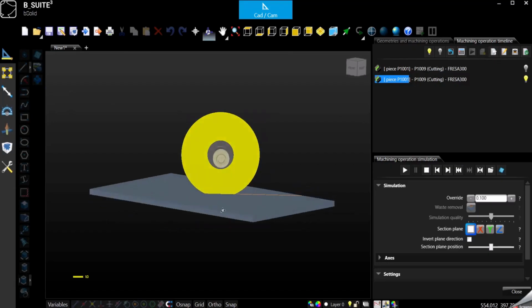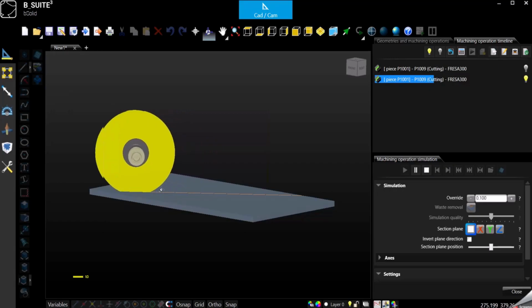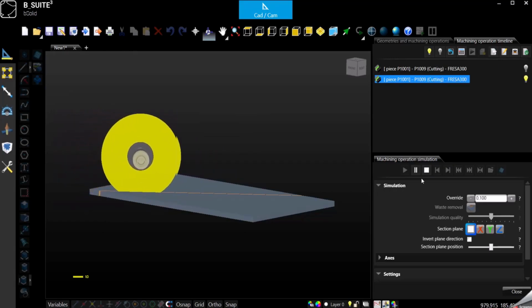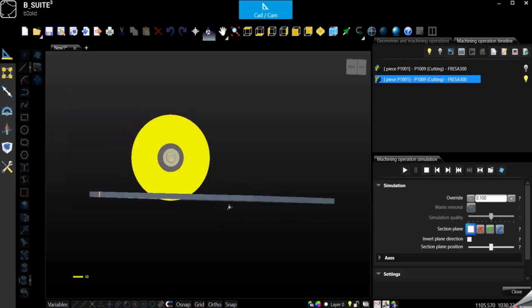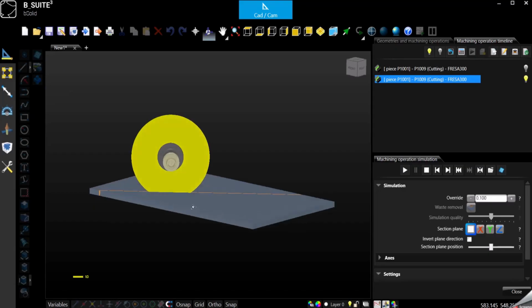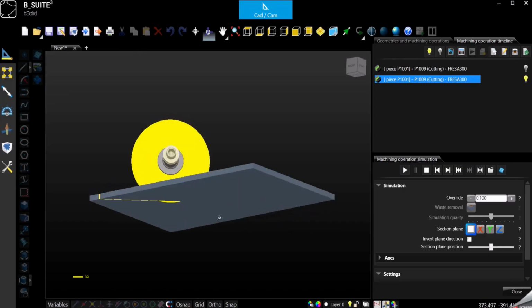And since I'm not all the way through, when the blade gets at the end, it goes down and comes back. So in this case, consider that I'm still spinning, of course, in the same direction, counterclockwise. In this case, my teeth will push up my melamine. Of course, the top is already cut, so it will not chip, and the bottom will not chip either.